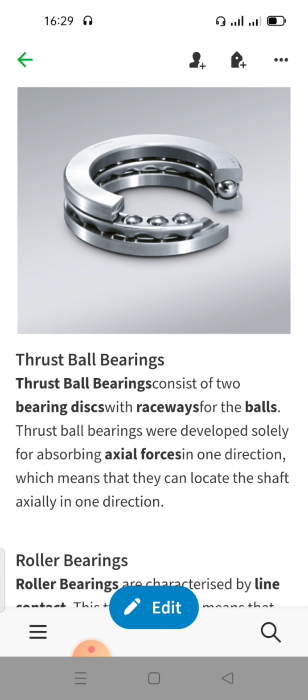Generally thrust bearing where there is a heavy axial forces, it is not for radial forces. When there is a heavy axial force, we have to use this bearing with other bearing, okay, or only this bearing, so this can absorb a very high axial force than any other ball bearing. In that case we should use this thrust ball bearing.